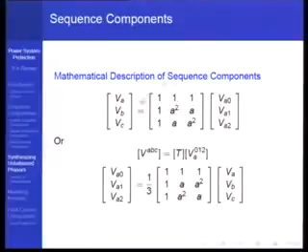So in that way you can check that all these rows and columns here are orthogonal to each other, but the length of each of the columns is not unity. The length is the square root of 3, and therefore, in terms of what we call power invariant transformations, this is not a power invariant transformation, because it's not an orthonormal matrix, even though it's an orthogonal matrix.